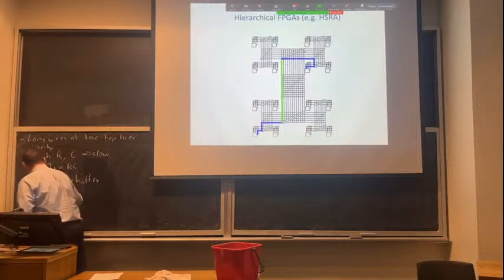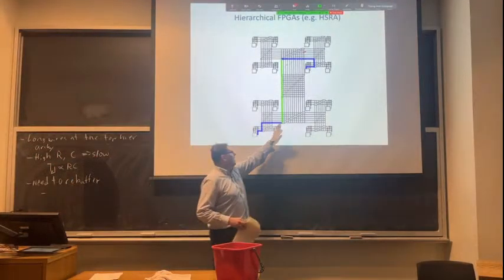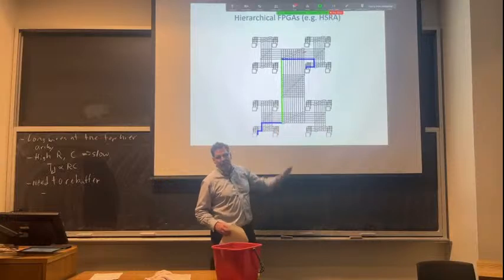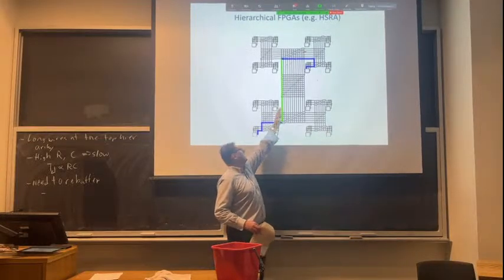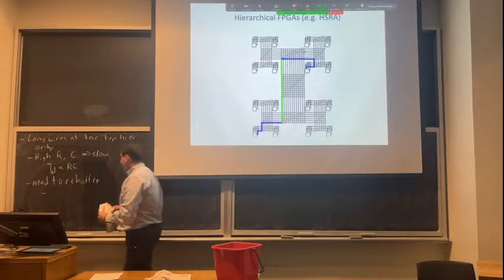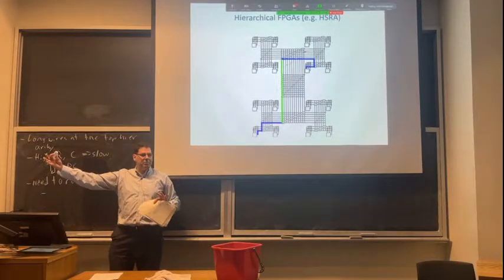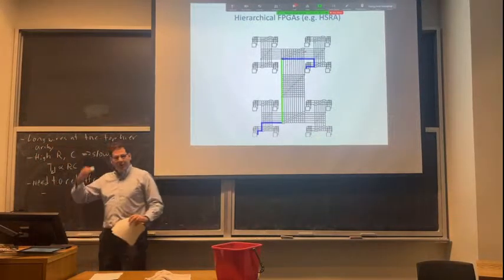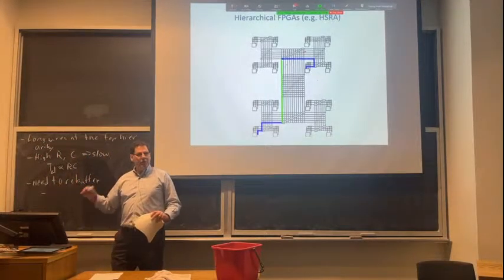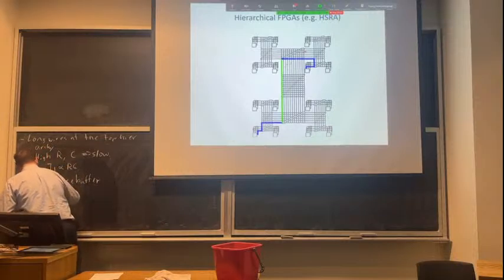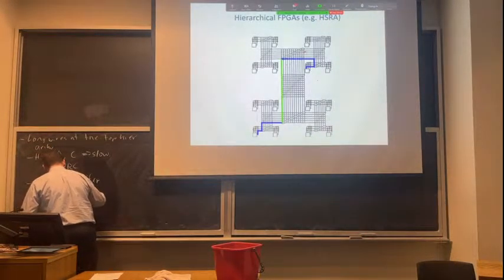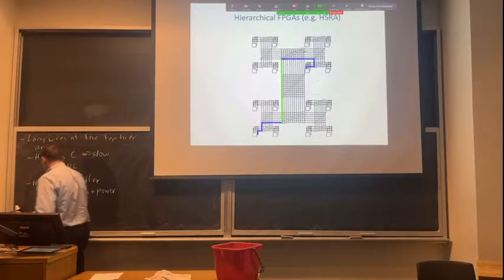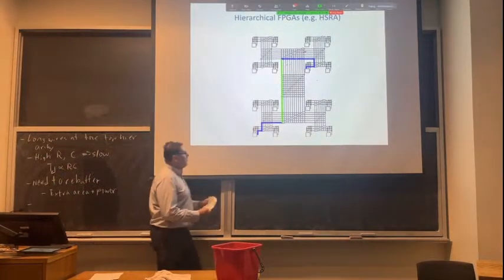Okay, so that'll stop the delay of this wire from getting, basically the delay of this wire grows quadratically with its length. So at a certain point, that becomes really slow. Like, you double the length of this wire and it gets 4 times slower. That's terrible because both the R and your C got twice as big because the wire's twice as long. So we can stop that quadratic growth by putting inverters in every once in a while, maybe every millimeter or 2. But that's going to cost us some extra area and power. But we're going to have to do it. But there's basically no great solution here.